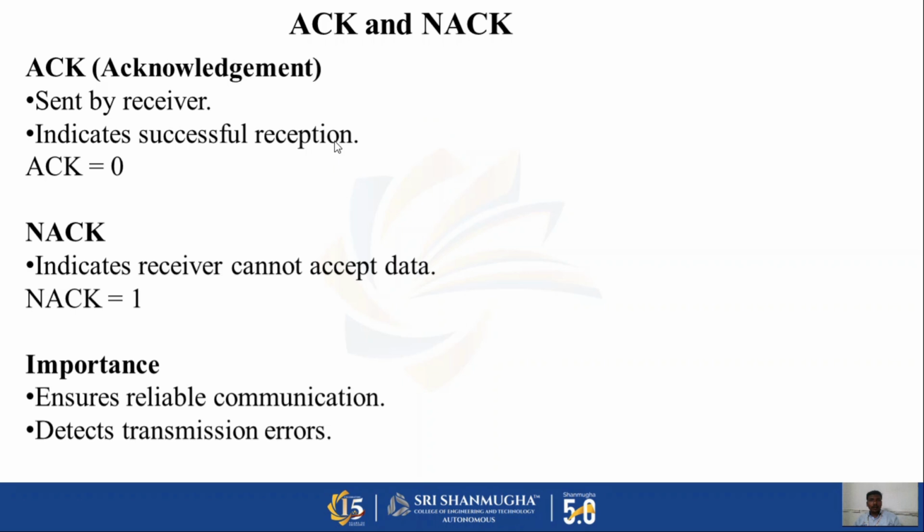Now let us discuss acknowledge and not acknowledge signals. ACK stands for acknowledge. It is represented by a logic 0. After receiving a byte successfully, the receiver pulls the SDA line low during the acknowledgement clock pulse. This tells the sender that communication can continue. NACK stands for not acknowledge.